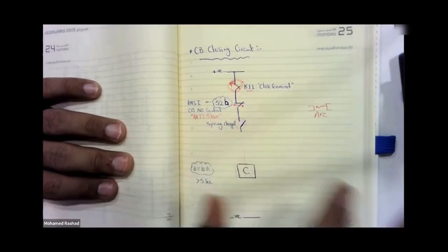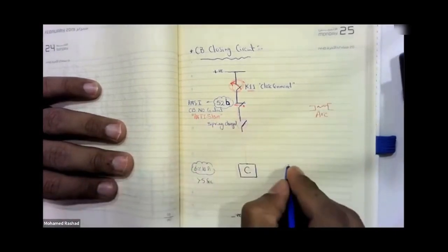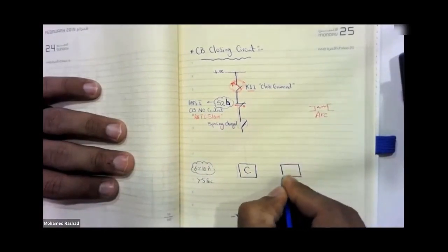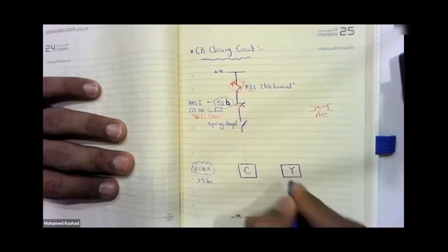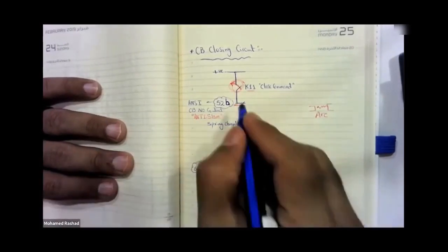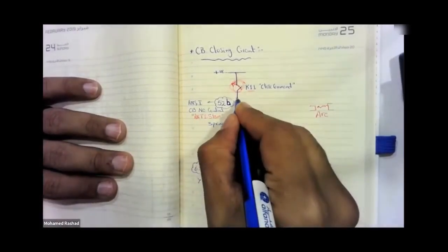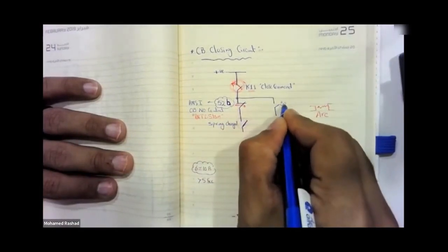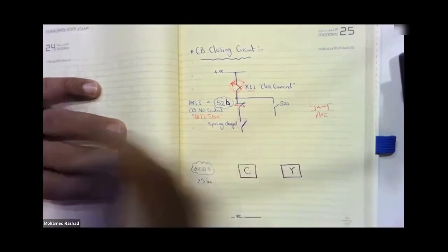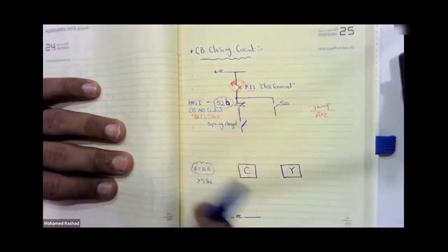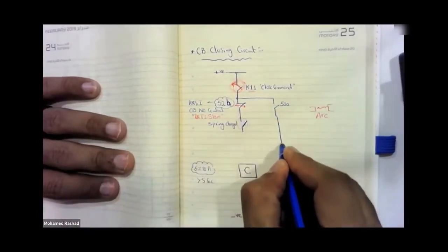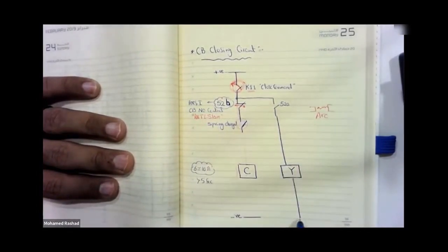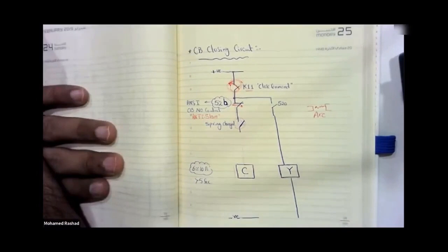They said it's very simple. They brought me an auxiliary relay here. All right. They isolated it for me and named it, for example, Y, or any nice name like that. And what did they do? They came here and took contact 52A from the circuit breaker status, all right? They took this 52A here and used it to operate the auxiliary, which is also connected to your same negative, all right?